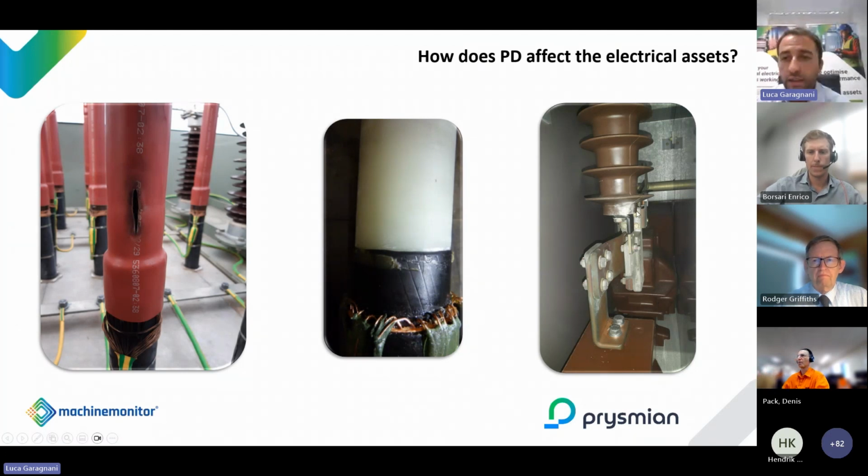This discharge is affecting the air of the cabinet, and since it's a closed cabinet, the air is limited and doesn't circulate, so all the air will be contaminated by ozone, and a high concentration of ozone with humidity will create acid. When you have acid, you start to have corrosion, and you can see all the components in this cabinet are corroded. The spout is corroded, the bar is corroded, so there is obviously a consequence of this discharge. Would that be detectable? Yes. From the moment the signal is triggered, any PD detector would detect this surface discharge.